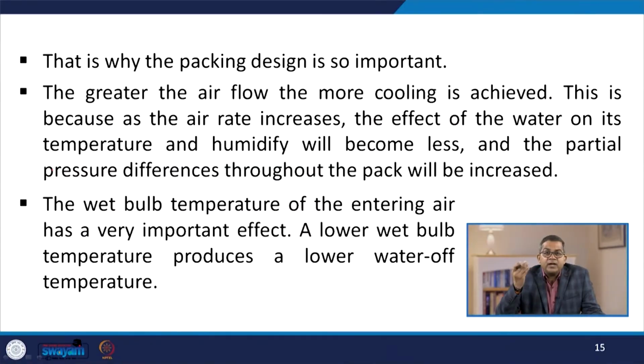The amount of evaporation which takes place depends on a number of factors, including the total surface area of the water presented to the air and the amount of air flowing. And that is why the packing design is so important. The greater the air flow, the more cooling is achieved, and this is because as the air rate increases, the effect of water on its temperature and humidification becomes less, and the partial pressure differences throughout the pack will be increased.